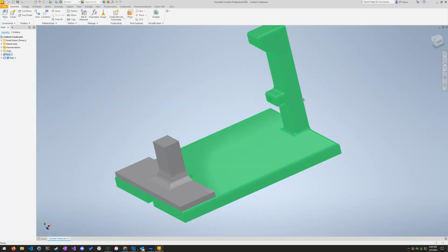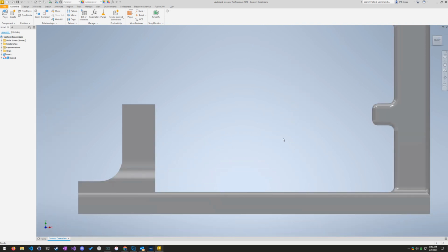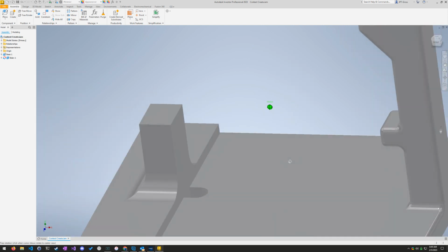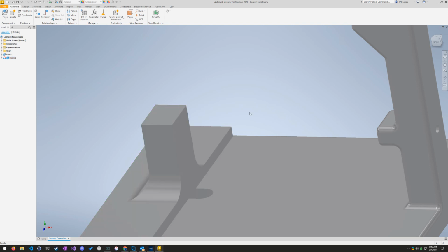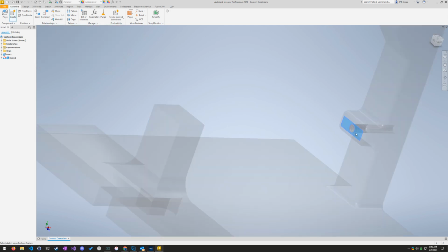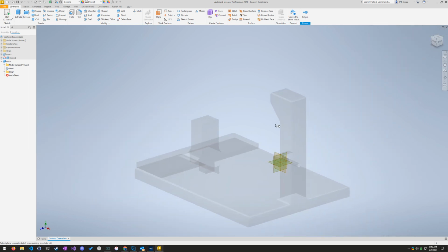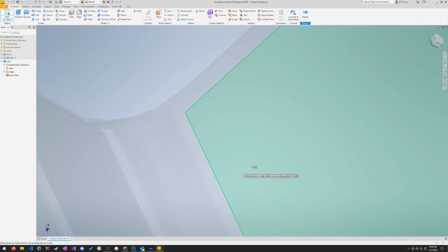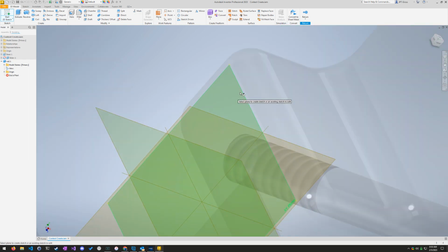Open. So we need to create a rod that's going to connect between these two surfaces, right? Boom, boom. So what we can do is on one surface, we can create a sketch, right? So what we'll do is we could just create a new component. I think it asks you to name that component something like rod, which I guess will make it easier for us to find, right? And we can click on that surface. When we start our sketch, we're going to start our sketch on that surface. Zoom in. Okay.